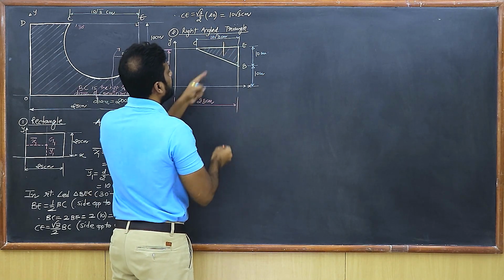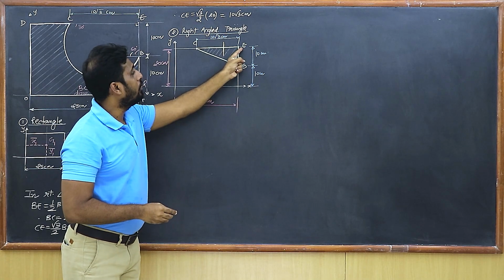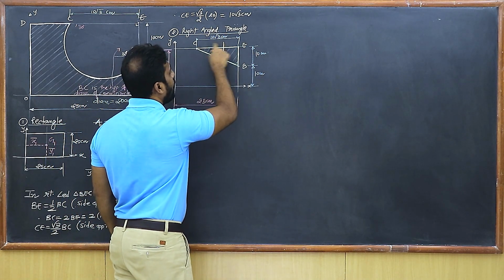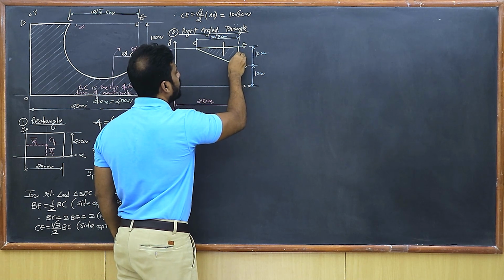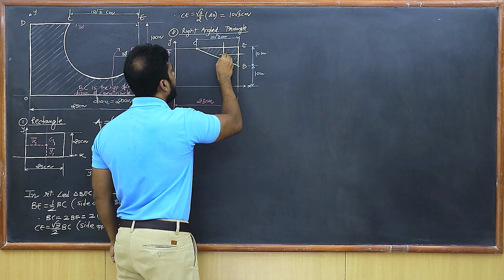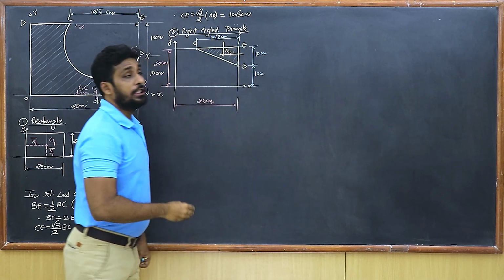So, this is the vertical line which is parallel to BE, the other perpendicular side. It is at a 1/3 distance from BE, isn't it? Similarly, you take BE, this is the perpendicular side. So you take 1/3 distance over here, and draw a line which is parallel to CE. Both of them intersect at a point which is the centroid. So I'm going to call this G2.